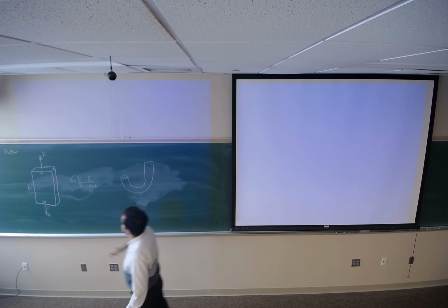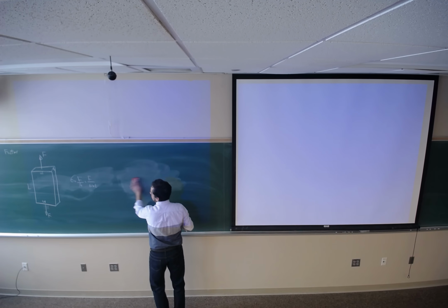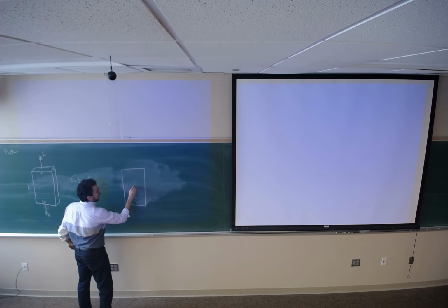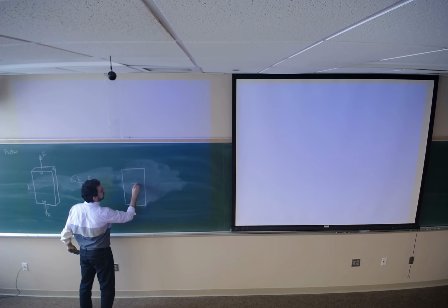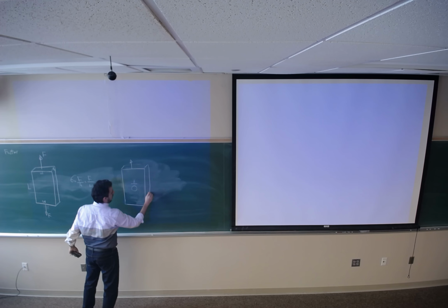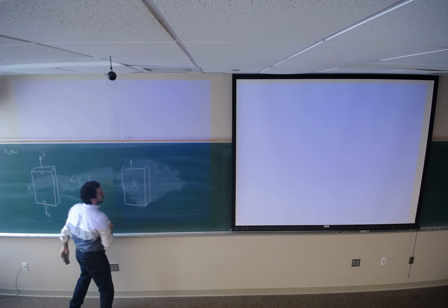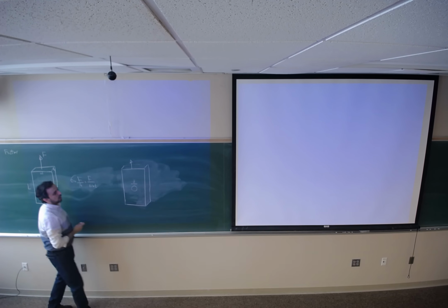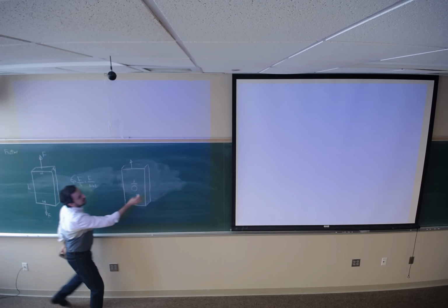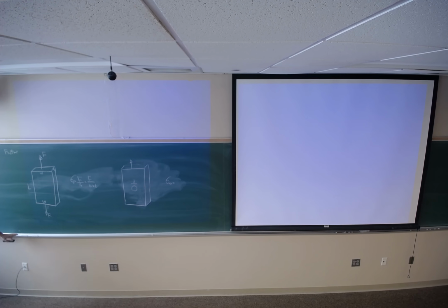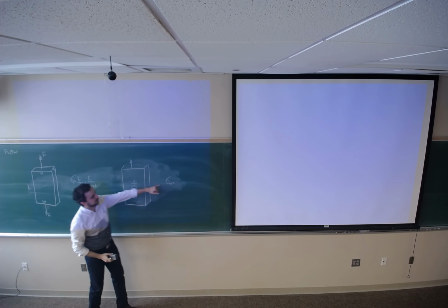Now I'm gonna add a hole at the middle with the diameter of D. Just consider a hole at the middle of this bar. We would like to find the nominal stress, I label it as sigma O, on this bar. At which cross section am I going to have the greatest normal stress?